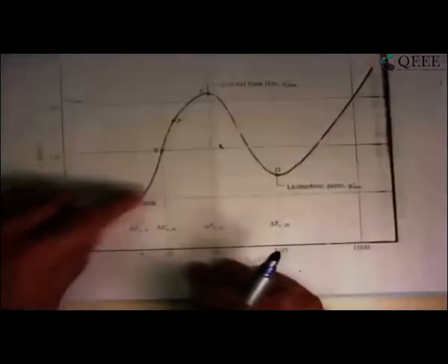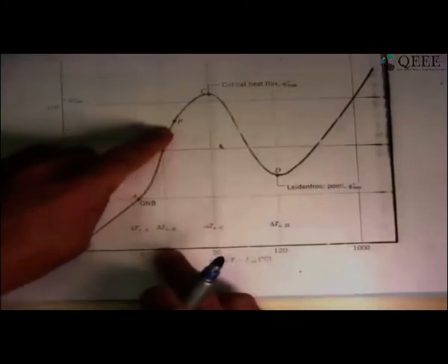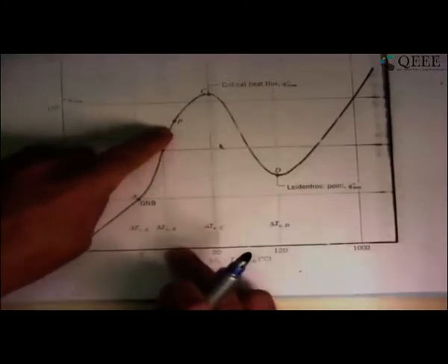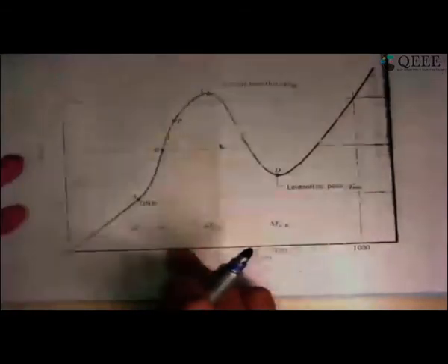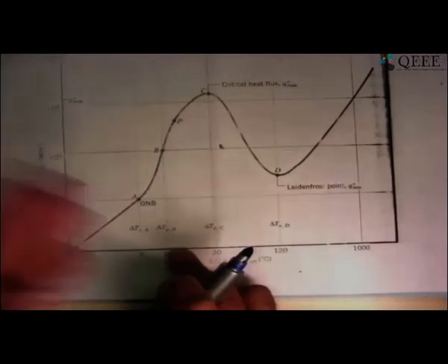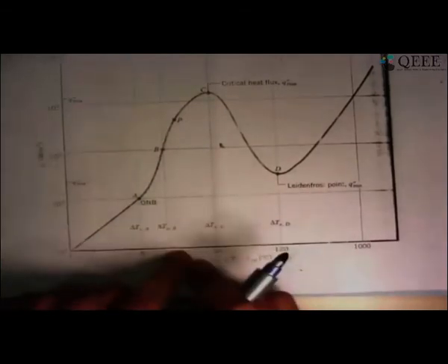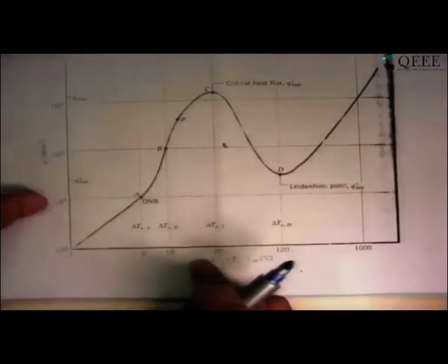So you are increasing the heat flux rate, you are getting this temperature. You are increasing this heat flux rate to this point, you will get this temperature, the average temperature of the wall. And this curve is the same for the constant heat flux case. Though, because of the random nature of the nucleation and bubbling process, the wall will be at the same average temperature that it would have been if the isothermal wall case had been there. So T and H in pool boiling are the same, unlike convection heat transfer that we learned.